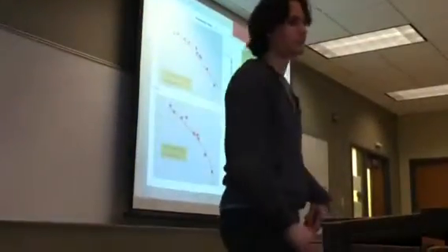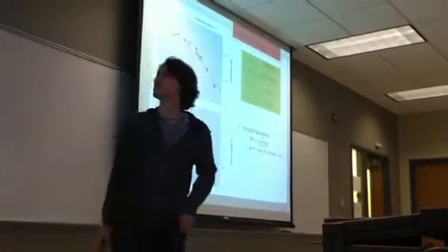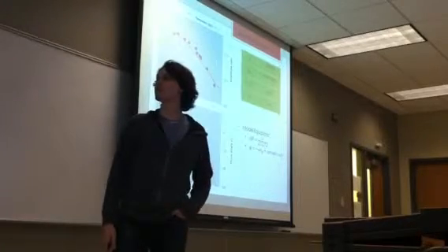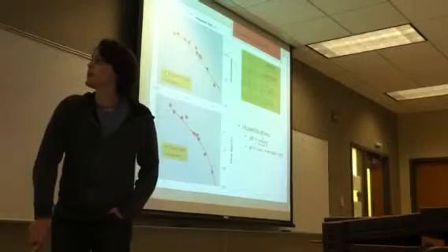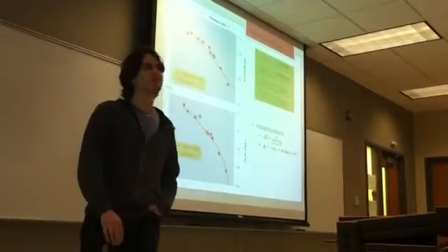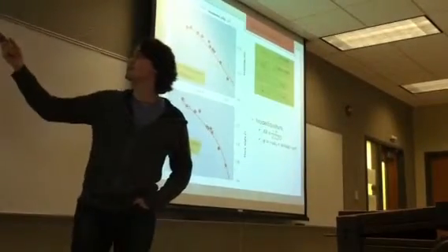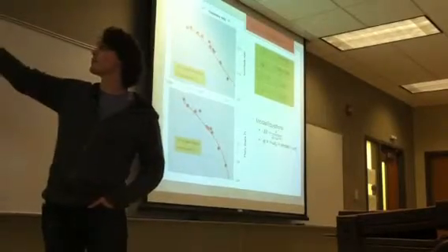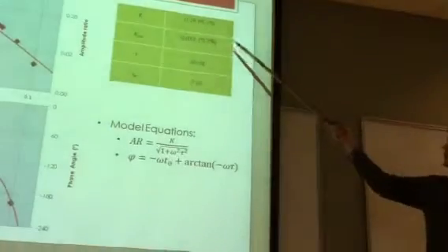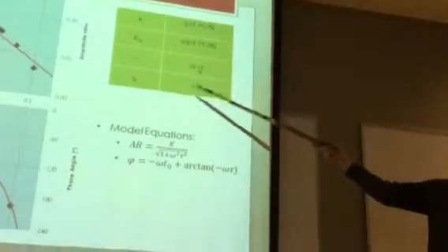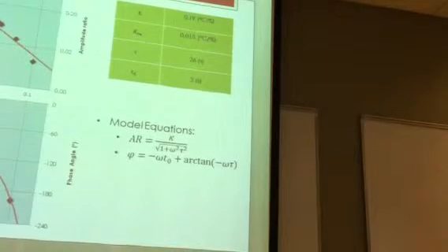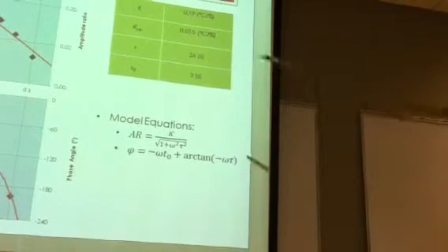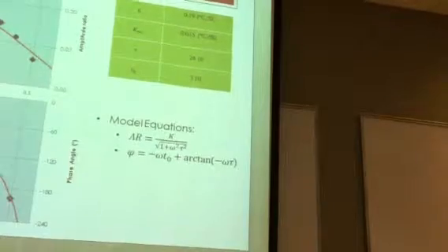All right, here's the fit method. This is new to our presentation. We used the model that was presented to us online to fit the data points. Here were the values that we got for our gain, our ultimate controller gain, tau, our time constant, and our dead time. There are the model equations that were used. You can see it fits pretty nicely, so we were happy with it.